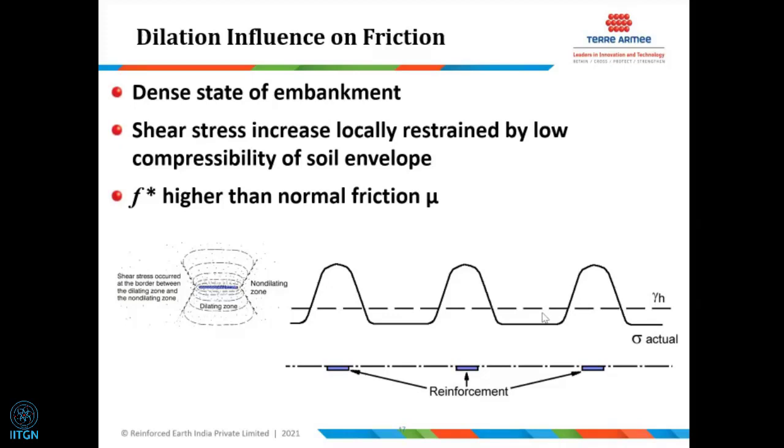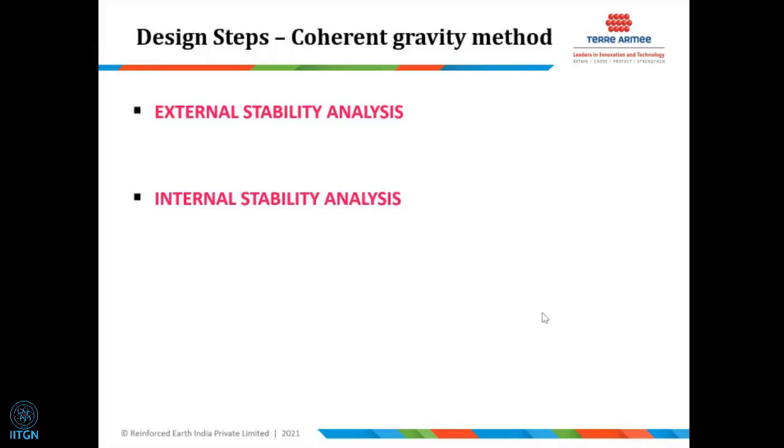This is important to understand, why the structure behaves like that. And the behavior is more because of the rigidity of the reinforcement and not just the elongation. So that's why I highlighted this particular behavior of this reinforcement. And this behavior is also there in some other kinds of reinforcement which are stiffer than steel. As I said, it is still not concluded in any of the guidelines.